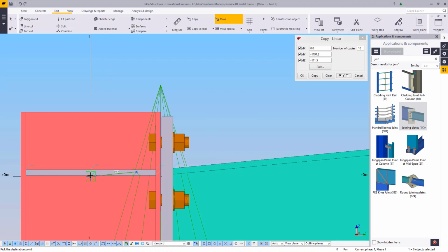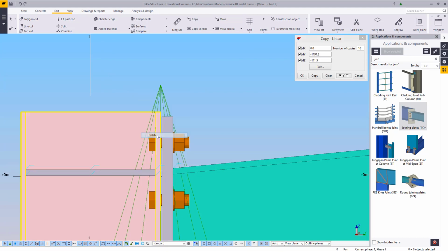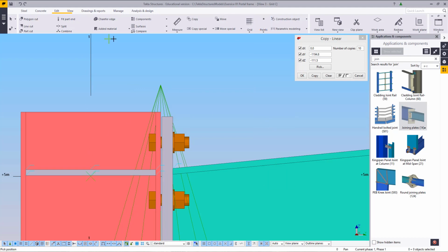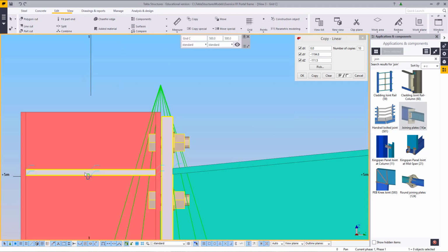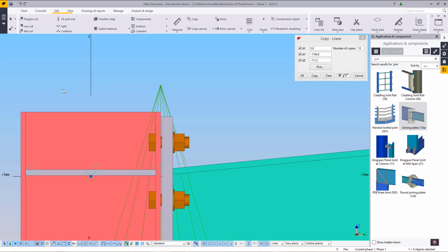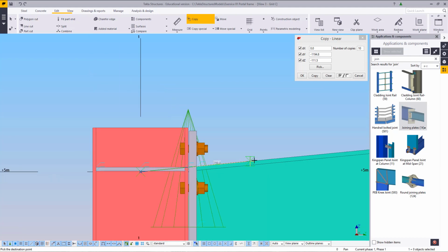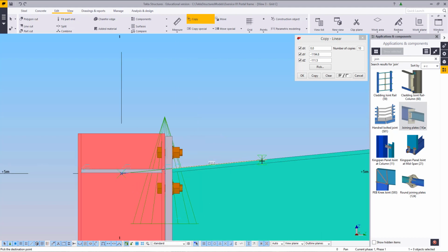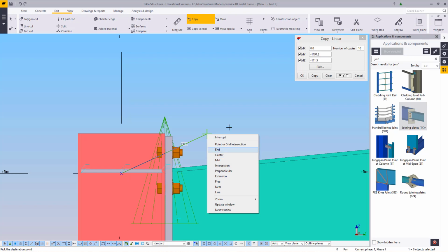Next, I'm going to take this bottom point and delete it. Afterwards, I'm going to say point at any position again. I'm going to take right there, point. Afterwards, select it, and I'm going to copy it upwards by 300. Now, as you see, the further you zoom back, the higher the number it snaps according to. Just get it snapping into the tens. There, put down 300.